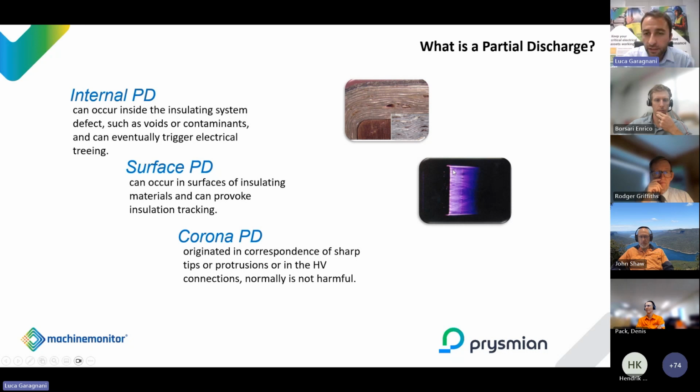Obviously the slot coating ends here, so the zero potential is here. After that, we have the high voltage, right? To mitigate the transition between zero potential, which is the slot coating, and the high voltage, which is the bar without screen, there must be a grading system, which is a semiconductive layer. That should be overlapping the slot coating to make the contact with the zero potential and extend along the bar to mitigate the surface stress. So we need to reduce the voltage on the surface of this bar.